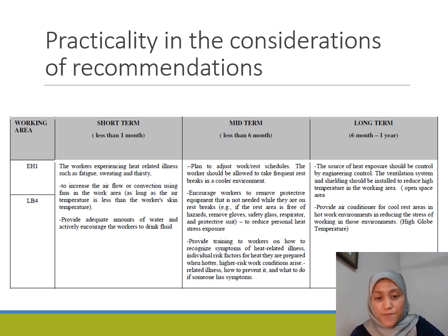And then for the mid term, plan to have work-rest schedules and also encourage workers to remove their PPE when they are in break time, and also provide training to give awareness to workers about what kinds of heat stress they are exposed to. And then for the long term, installation of engineering controls and also air conditioning. Okay, so here is what is recommended based on the result.